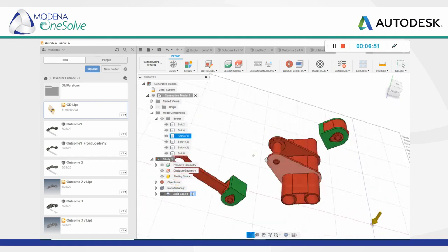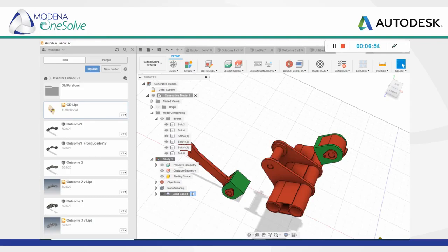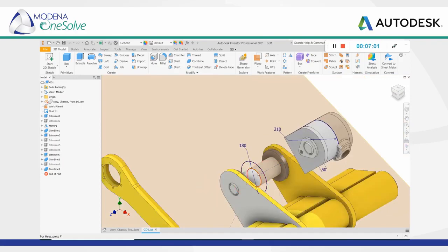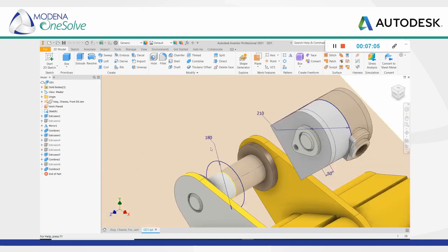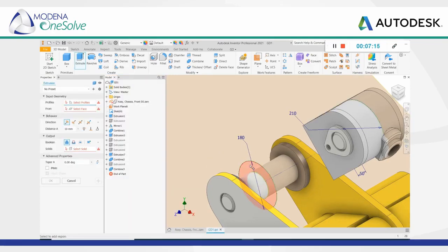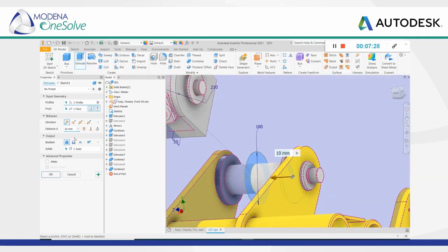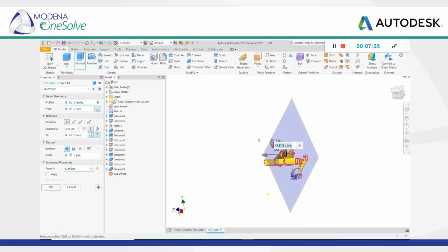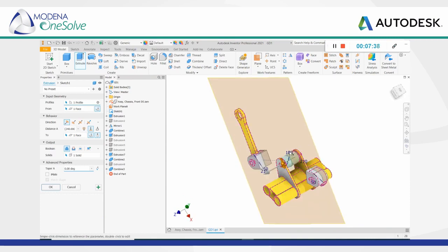It's bi-directional. Okay, so that part still needs to be created, and what I'm going to do is head over to Fusion and make those design changes and quickly create the pivot axis for the arm over here. Okay, so what's going to fit around this axis? It's going to be a solid body, and I can design that relatively quickly by running an extrude. Okay, so that component's going to extend from this face, and it's going to go all the way up until that point over there. And let's just rotate this a little bit.